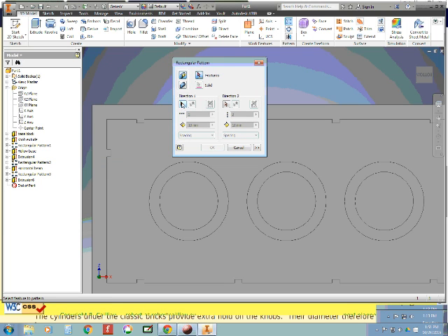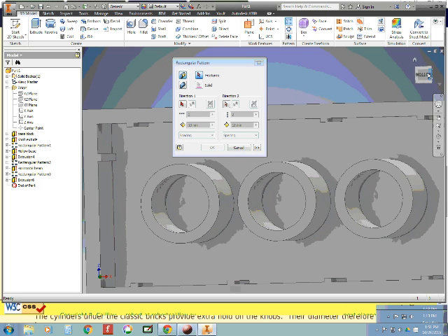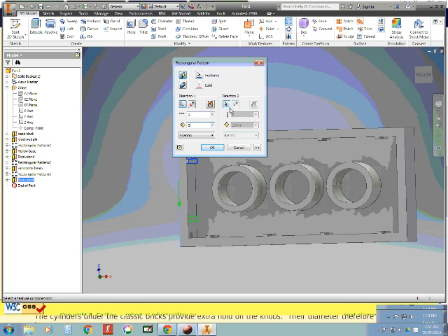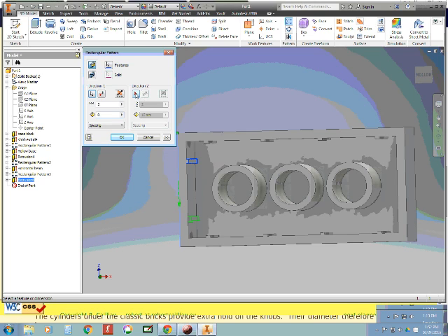Okay, so the feature I want is this one, and let me rotate that so that it will let me grab that. This is the feature that I want, and the direction is this way. We want 2, and remember they're 8 millimeters apart. Let's zoom out a little bit, and then the second direction is this way, and again I want 2 of those, but that distance, once again, the 31.8 minus 1.2 minus 1.2 minus the thickness of the beam.